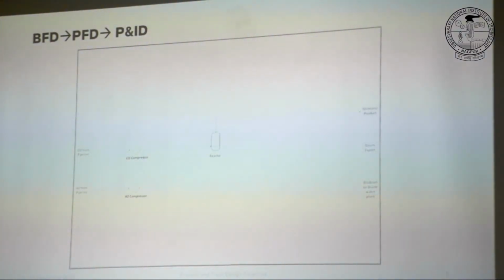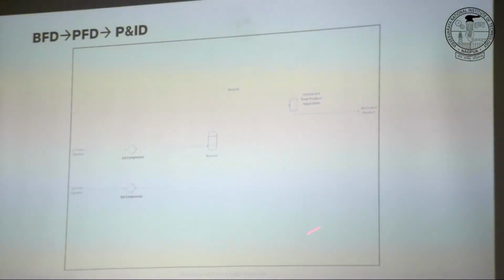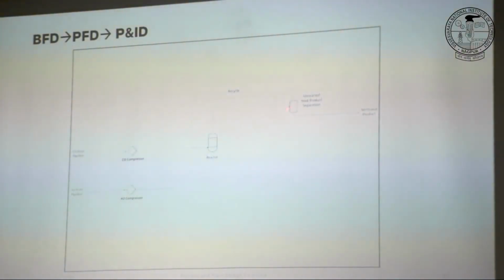At this point, I already thought about the heat integration. Looking at the reaction, it's exothermic, so a lot of energy will be released at an appropriate temperature. We extract energy via steam production. So steam is generated somewhere here and it's exported. Suddenly we had two reactants and one product, but now we have a second product as well. Products are formed, and then we separate it, and then you have the product.